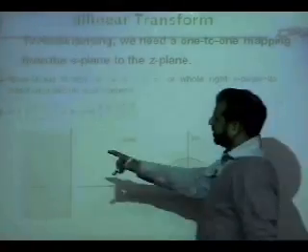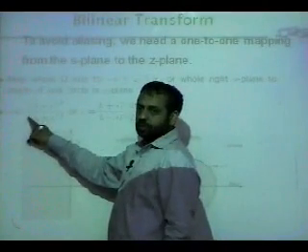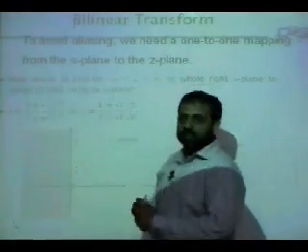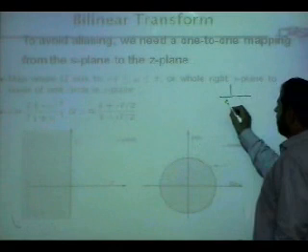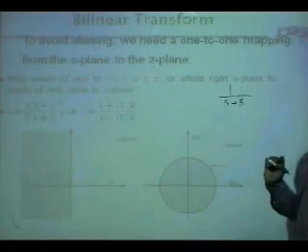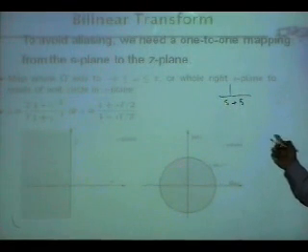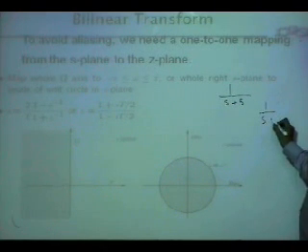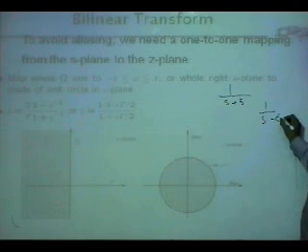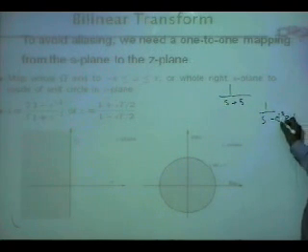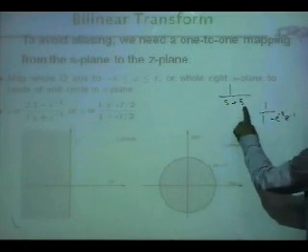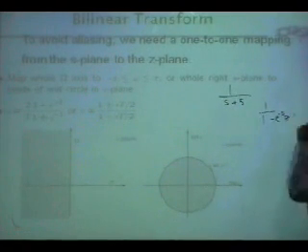And in this, you can assume capital T is equal to 2, so that the 2 cancels out with 2. This is 1 minus Z inverse over 1 plus Z inverse. For example, the last time we did an example, 1 over S plus 5. And we said it is very simple. In the Z domain, it is 1 over 1 minus exponential minus 5 Z inverse. So this was the expression in H of Z. Remember? So we said it is simple. A pole here will be a pole at exponential minus 5.